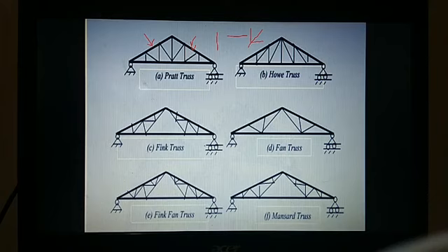The internal forces you are going to assess are in terms of supporting the main top chord and bottom chord members. When a member is resisting on its own, as you said, the internal forces in the internal members will be zero, but internal members will also have internal forces. That is what you are going to assess with the help of the method of joints and the method of sections.